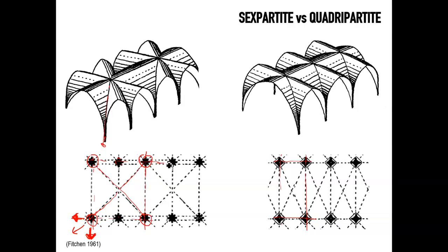So, for example, if this bay was built first, there would have been a time where the thrust coming from these diagonal ribs, particularly if the ceiling is very high, could have required a lot of props, a lot of temporary works, to prevent this pier from collapsing this way until the next rib comes into place.